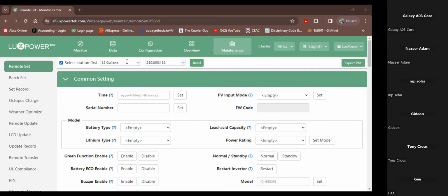So if you measure the potential difference across there, you take a single solar panel and put it in the sun, and the MC4 connectors are not connected to anything, they're just dangling there. You take your leads on your tester and measure the potential difference between the two. The conditions are clear: the panel is angled at 33 degrees, the sun is great and it's a nice cool day, and you get 48 volts. The minute you close the circuit, in other words, you put resistance across the circuit and draw power, which means the amps will go up, the voltage will come down.